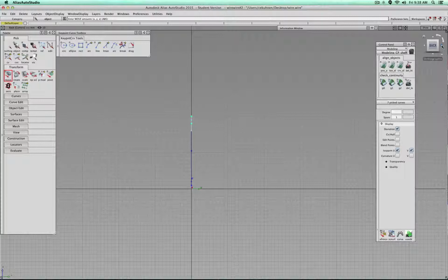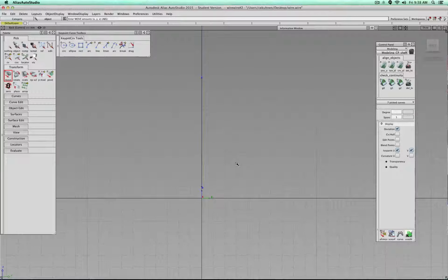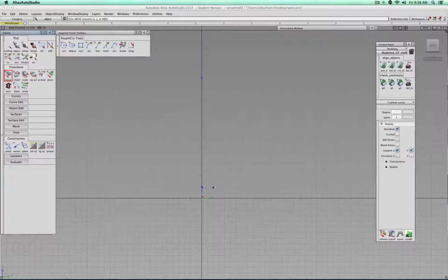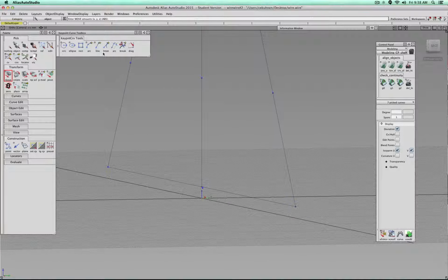Now our blade has a 2mm, it has a 1mm thickness, and there is going to be a cutting part. So we can take maybe care of that one. So now you see I have a 1mm block. Later we're going to extrude the surface out this way. So I know that maybe there I need a little bit more of detail. So I changed my subdivision to 20. So now I see exactly the millimeter, half millimeter, millimeter, half millimeter breaks. Great.